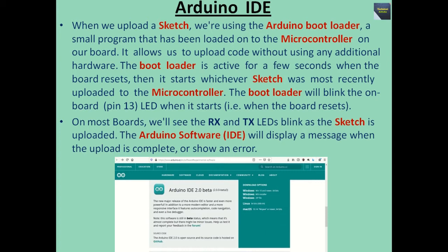The bootloader will blink the onboard pin number 13 LED when it starts, which means when the board resets. On most boards, we will see the RX and TX LEDs blink as the sketch is uploaded. The Arduino IDE will display a message when the upload is complete or show an error. And now I will open the Arduino IDE and write some sketch onto it.